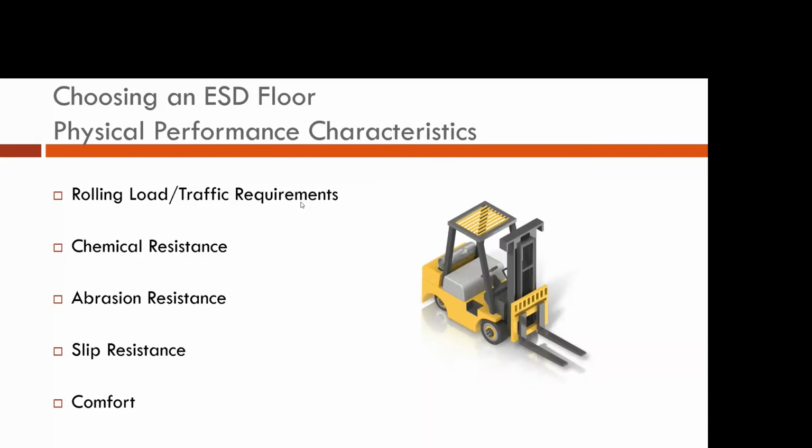And the last thing you want to understand from an ergonomic human capital standpoint is comfort of that floor. Standing on a concrete floor all day long, it wears down on you over time. Standing on what folks like to call anti-fatigue, it feels super comfy when you're standing on it because you sink down into it. But when you go to turn and pivot and move, that material actually grabs onto the soles of people's shoes and it causes them to exert more force on their joints when they twist and bend and turn and move.